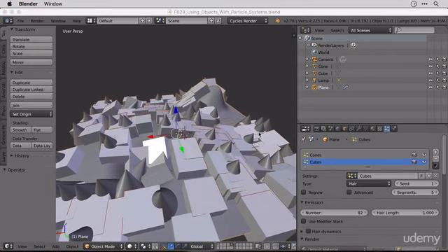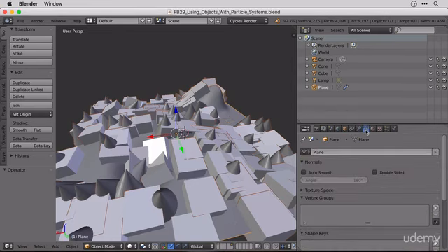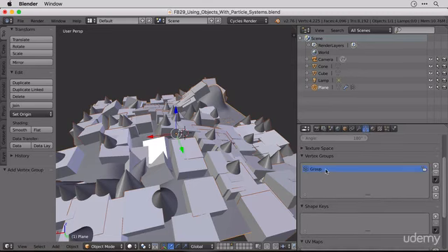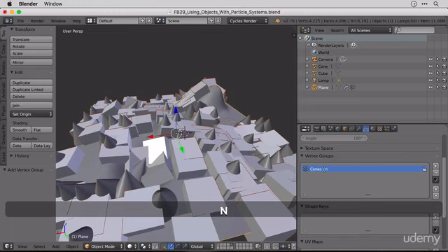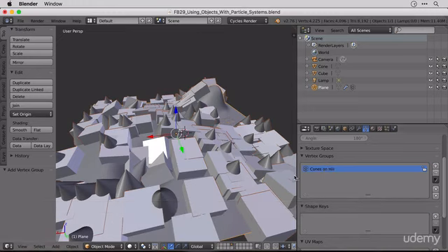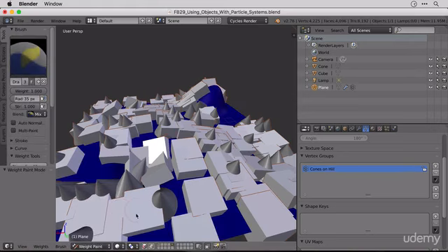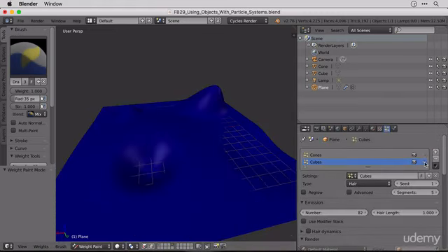of one another. So the one final thing, just like with the bunny, you can use weight painting as well. So say we wanted only these cones to be on the hilly parts of our mesh here. We would make sure the mesh is selected. We'd go to the object data properties over here, and let's scroll down and we'd add a vertex group, and I'm going to call it cones on hill. It's always good to name it round this way, and then immediately switch into weight painting. I'm going to turn off our particle system so I can see what's going on.